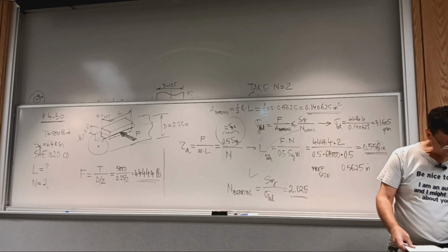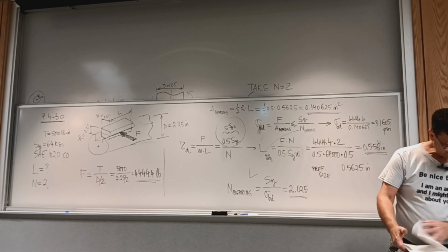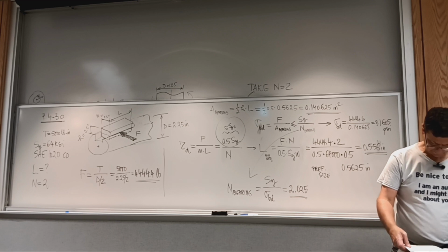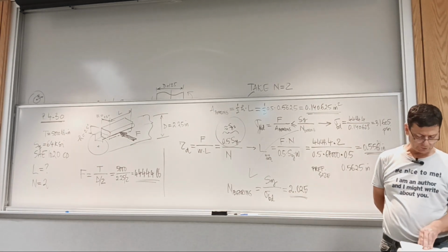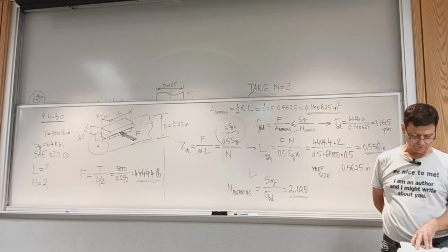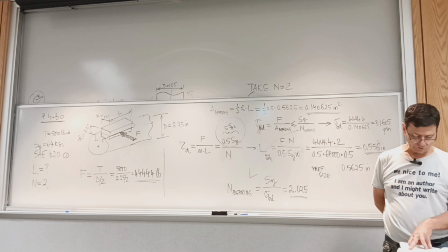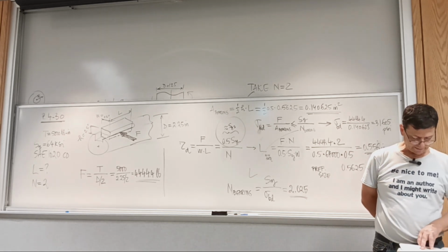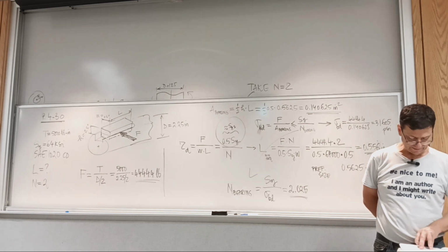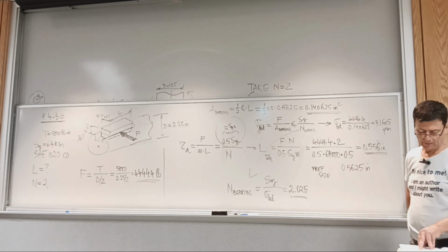We passed it. So design bearing stress for aluminum, and then we have aluminum. Where is it? Okay, for steel, it says, according to the American Institute of Steel Construction, reference on page 177, this is chapter 3. The allowable bearing stress in steel for flat surfaces or on the projected area of pins in reamed, drilled and bored holes is 0.9 times yield strength.